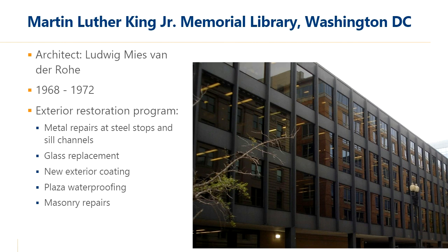So going back to what Martina showed on the previous slide, the reflections of the adjacent building, which we know has straight walls, that show a bow or a distorted image in the glass reflection are heat-treated replacement units. So looking at this photo, based on this, we believe that all of these windows were replaced at some point. So I'll remove those outlines so you can take a look at the reflections again.